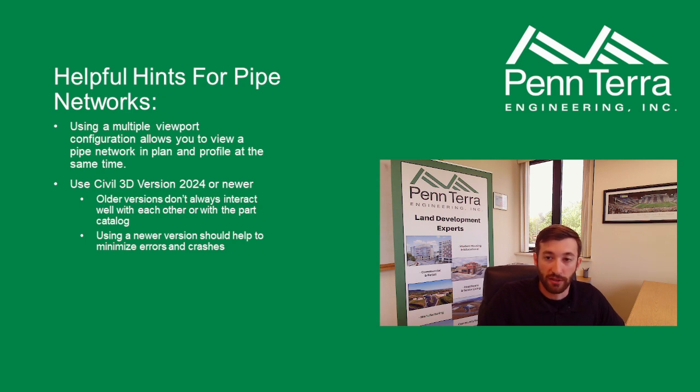Okay, a couple helpful hints before we get into the meat and potatoes of it. Using the multiple viewport configuration setting is really useful whenever you're doing pipe networks. I'm going to show that if anyone hasn't used it before. It's also really useful for other aspects of Civil 3D like road design because you can show your plan and profile at the same time.